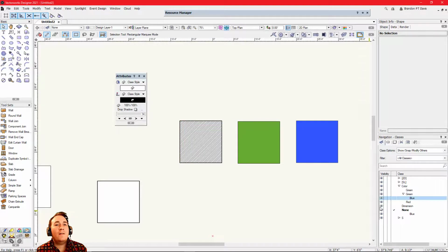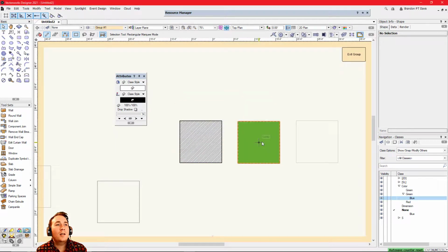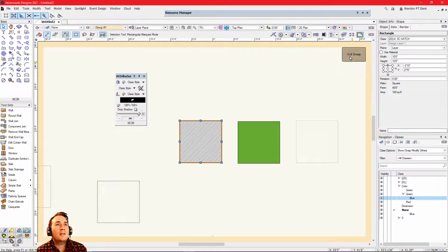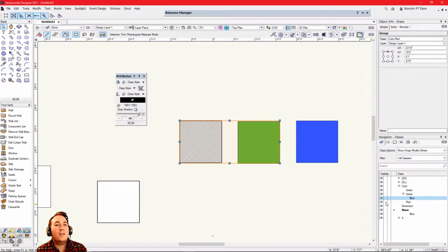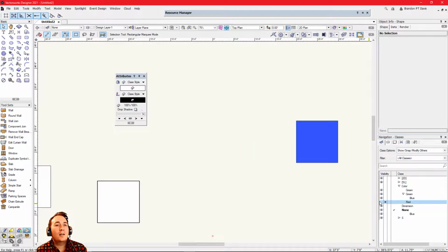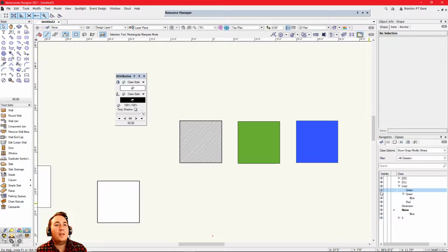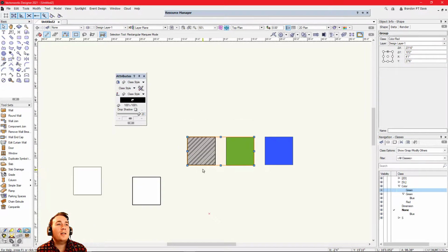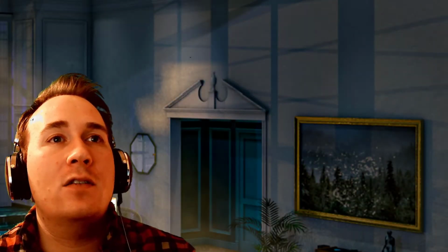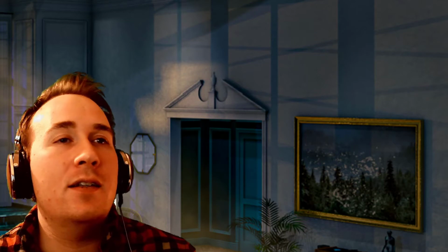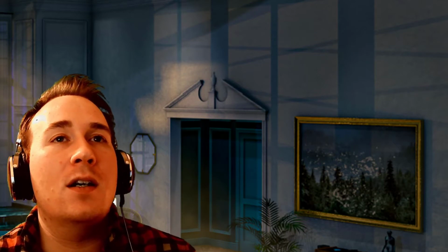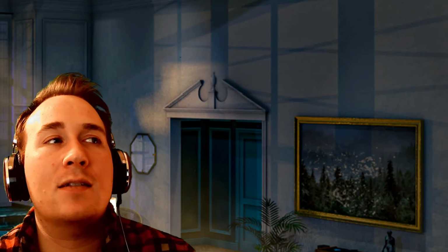By doing this, I have the ability to have two different classed objects within the group, but I can change the visibility of the group together. Also, if you were to modify the class within the group, it will be affected independently. This can become quite useful in more complex projects. This concludes the portion of the tutorial covering classes. The next section of this tutorial will be on the design layer aspect of Vectorworks.